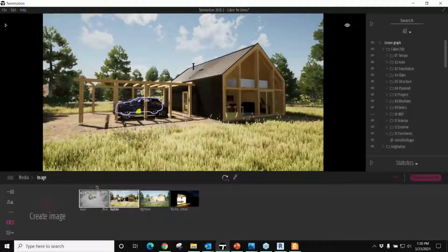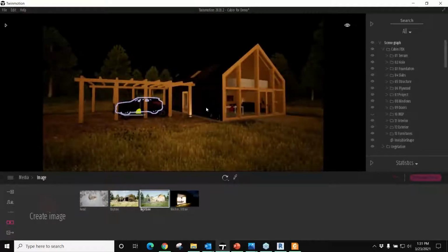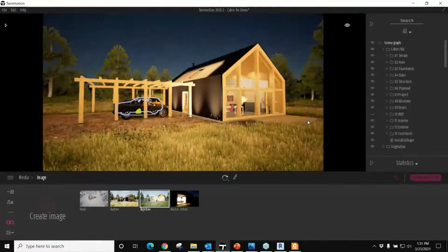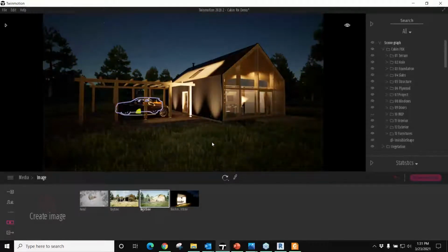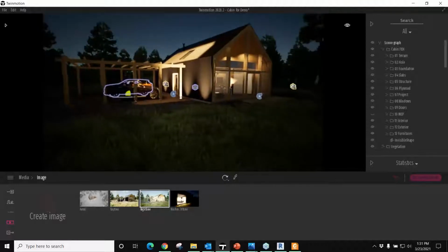So beyond the daytime renderings, you also have the option to place artificial lighting. So I've done that in this file, and the exposure control is catching up to it. There we go. So as you're changing between times of the day, there are some really cool triggers if you have artificial lighting, like the uplighting I put on the outside of the building here. Hit this button G. These are called helpers. So keyboard shortcut, you can turn those on and off.